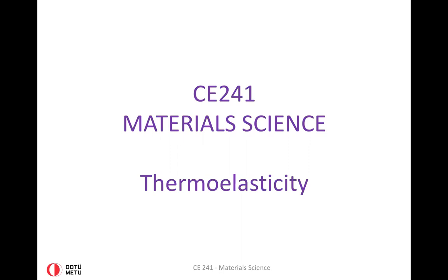In this video lecture, we will talk about thermoelasticity. This is a phenomenon that defines thermoelastic coupling. In other words, the effect of the temperature on the mechanical deformation of materials, and also the effect of the deformation on the temperature evolution within the material. This is typically observed as deviation from ideal linear elastic behavior of materials in the stress strain curves.